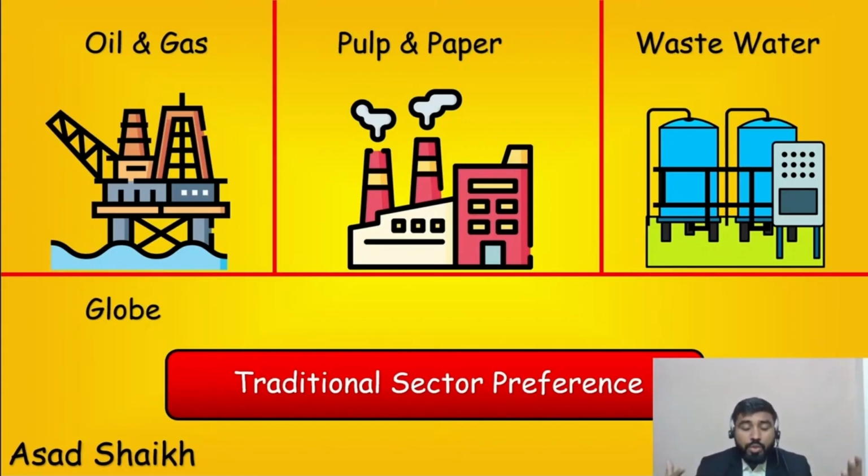In oil and gas you also have utility sections where you will have water transporting. There, if you see a globe valve, you can definitely try to replace it with a butterfly valve, save cost, and maybe add value as an engineer in the project. But overall, because oil and gas projects are generally more challenging in terms of the differential pressures you will face, for example an ethane cracker, you would see that engineers usually recommend a globe valve.